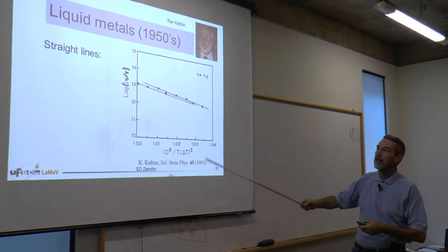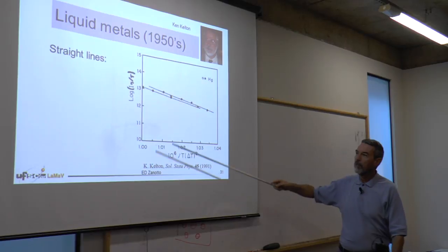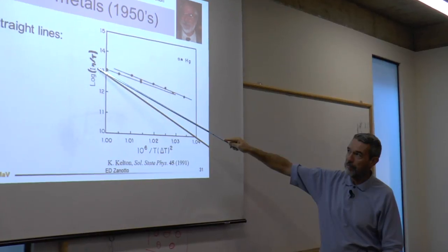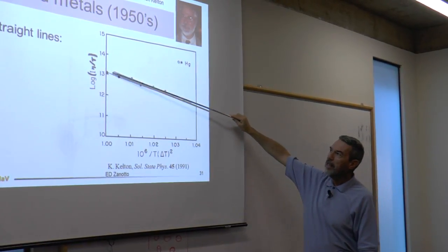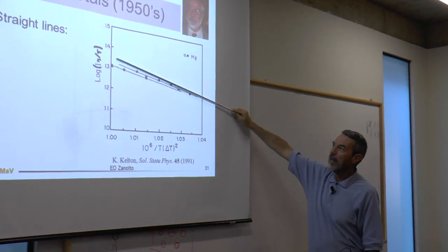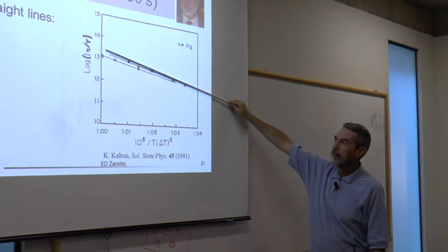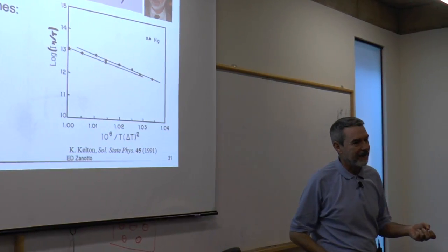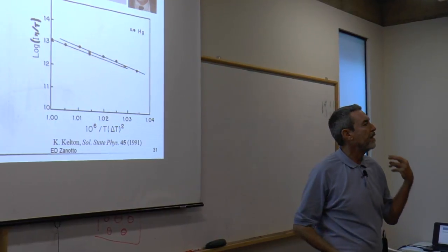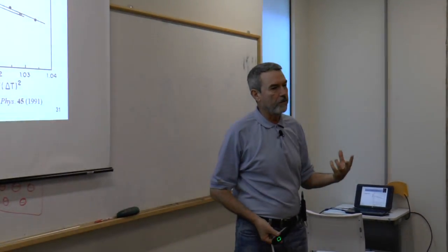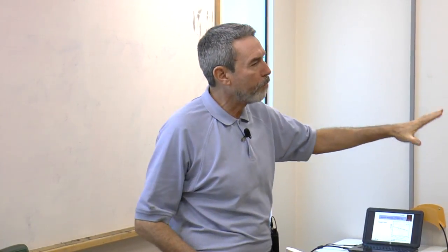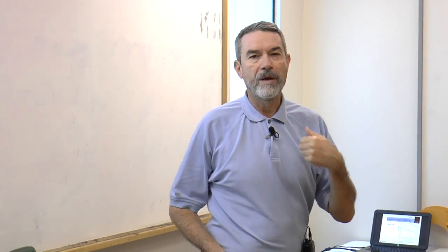And to test the theory, there are several ways, but one way is to plot the log of the nucleation rates times viscosity over T. And he did get straight lines for 2 sets of experiments. In any good research, you have to repeat your experiments, and Professor Turnbull did that, especially when you're dealing with very complicated phenomena. You will have to at least repeat once. This is a general rule of science. Experiments must be reproducible.